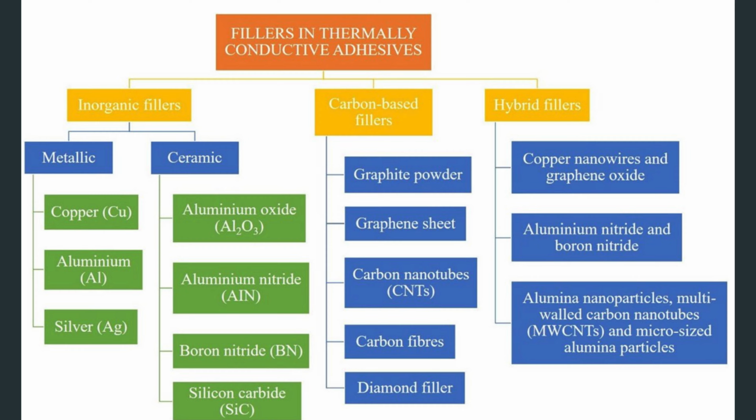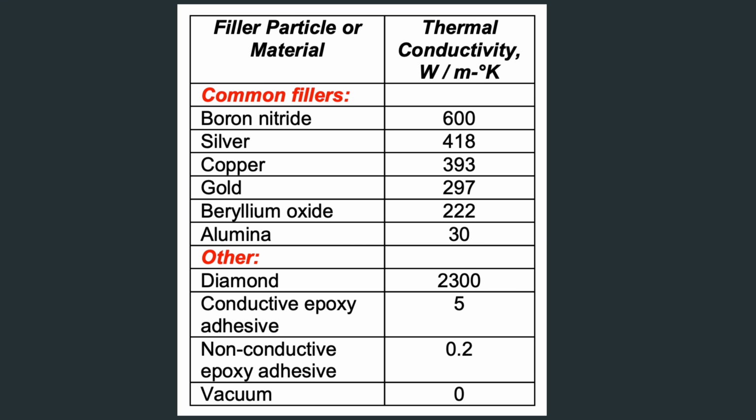During polymer matrix curing, resin shrinkage often occurs, bringing filler particles into closer contact. This increased particle-particle interaction further enhances heat transfer, and thus the final thermal conductivity of the adhesive is typically determined after curing is complete. Thermal fillers may be metallic, ceramic, or carbon-based.